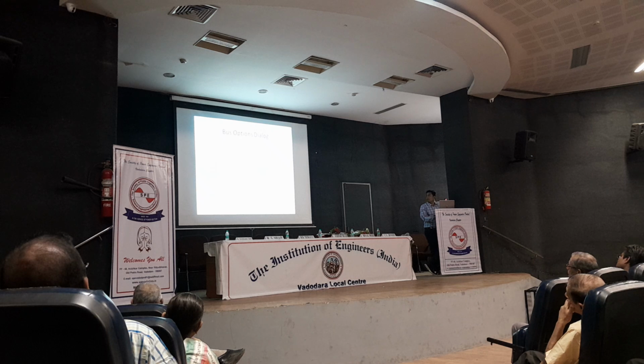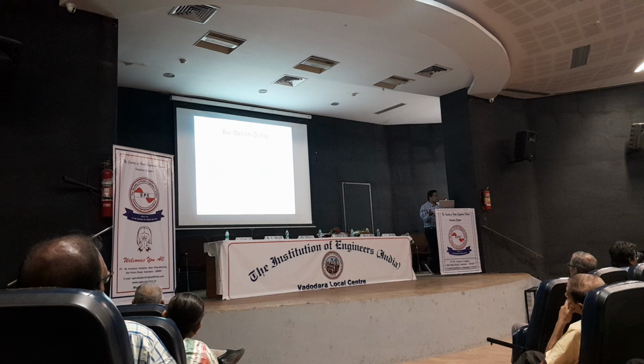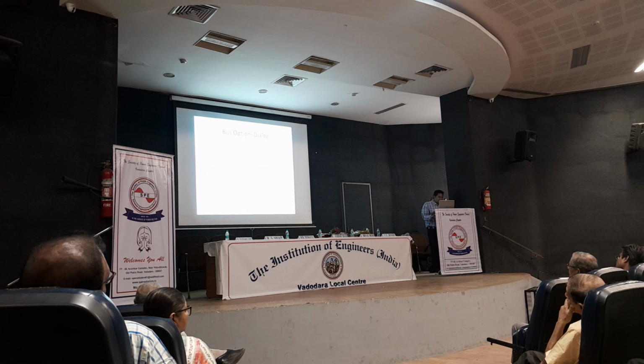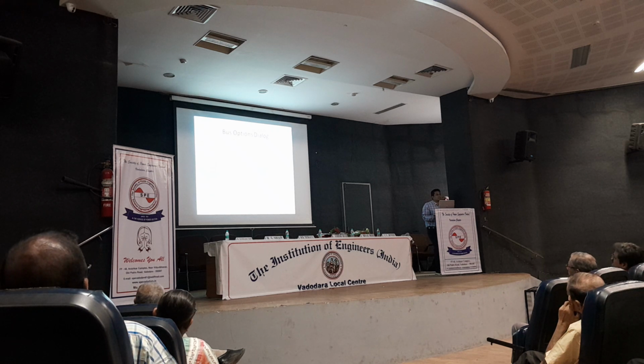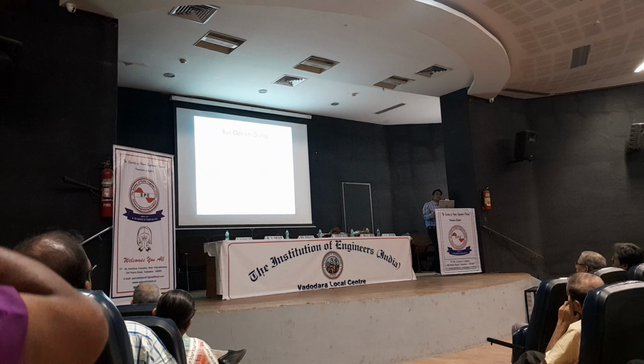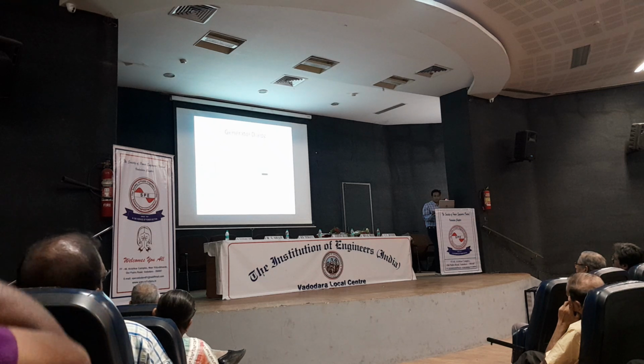If you pay attention to the second slide here, maybe the majority of you are dealing with electrical engineering, so you have the idea that whenever we are doing load flow analysis, one bus we have to select as the slack bus. Generally a bus which is connected to a generator, we select as the slack bus so that we can go for the solution. So here is one checkbox. If we select that checkbox, we can make one particular bus the slack bus, and then we are going to attach a generator to this bus.